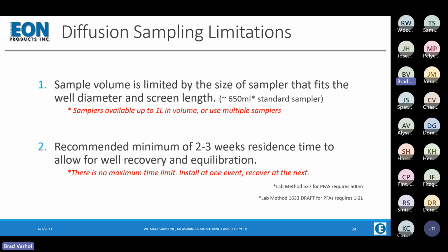The good news is that there's no maximum time limit. Because it stays in dynamic equilibrium with the formation and the aquifer water, we can install the samplers at one event and just go away for a month, a quarter, a year, or 2 years or longer. And when we come back, the sampler that we pull out of the well will represent exactly the concentration of the water over the last few days. So that means we can install a sampler at one event, and when we recover it, we can put another sampler in, making it ready for the next event. So we don't have a second mobilization.